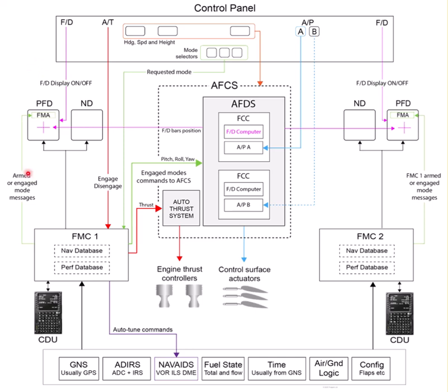Just remember that the FMS is everything that we see on this screen, and it includes the autopilot, the flight director, the auto thrust system, and the FMCs and CDUs. It's just a generic name for the whole thing. And the control panel here is what allows us to effectively tell the system what it is we want. Do we want nothing, or do we want everything? Do we want the full LNAV, VNAV package?